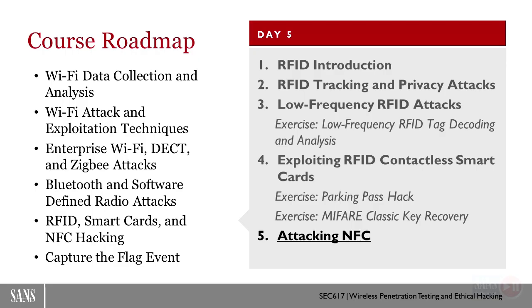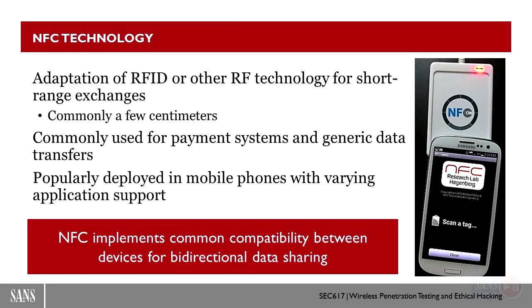All right, so let's take a look at NFC and its adaptation for using high-frequency communication for our RFID tags and how we end up using it. NFC gives us the ability to use high-frequency RFID with multiple reads, the ability for us to change direction between the PICC and the PCD dynamically for doing significantly larger data transfers, and the ability for us to use this for some authenticated means for payment card transfers.